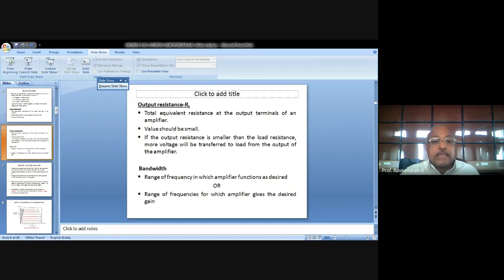A transistor is essentially a device having two junctions. The junctions are always subjected to temperature because it is carrying power, isn't it? The output side of the transistor, that is the collector-base junction, has a high current flow due to amplification, isn't it? So that causes high heat dissipation on the collector side. So the temperature at the collector-base junction may increase or decrease depending upon the collector current, isn't it?